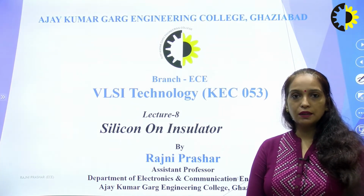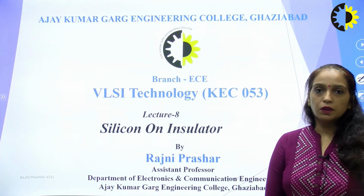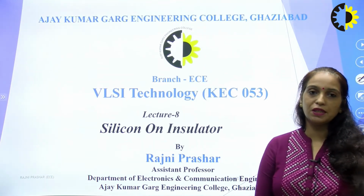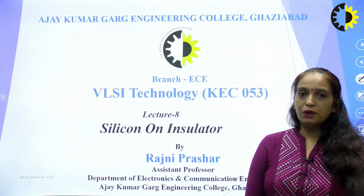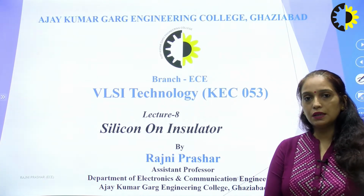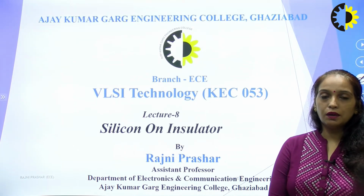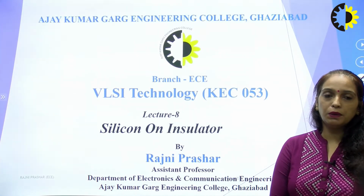Because we know that silicon's melting point is very high, we cannot use liquid phase epitaxy to grow the epitaxial layer over silicon. So to grow the epitaxial layer over silicon, we always need vapor phase epitaxy or molecular beam epitaxy. And the difference between these two processes is that vapor phase epitaxy is carried out at very high temperature, whereas molecular beam epitaxy is generally carried out at low temperature, and we can have a very thin epitaxial layer with the help of molecular beam epitaxy, right?